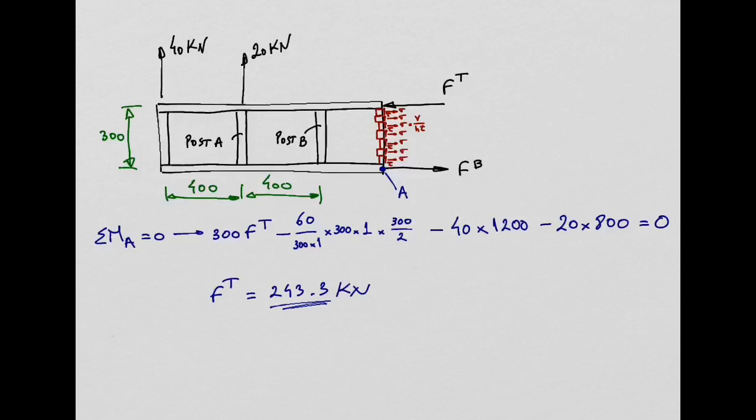So one important thing is this term here comes from the contribution of the developed diagonal tension field, yeah, after buckling. While these two terms here, they come from the bending of the beam, right? Because of these two forces. So you can see that after the development of the diagonal tension field, this term here is adding more to the force in the top flange, isn't it?